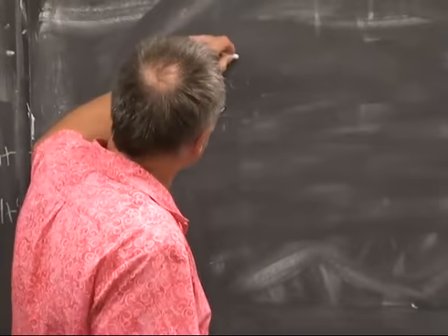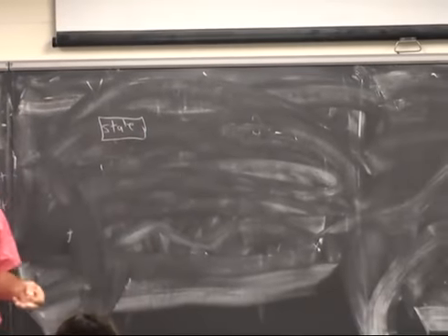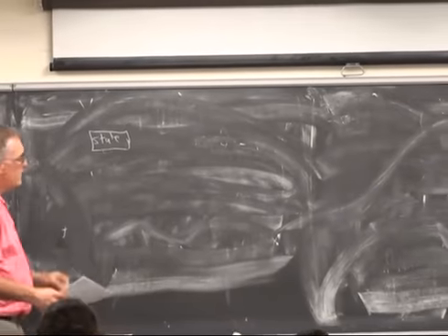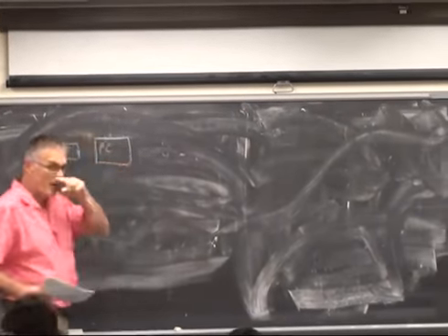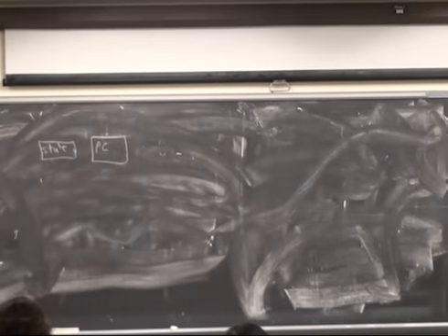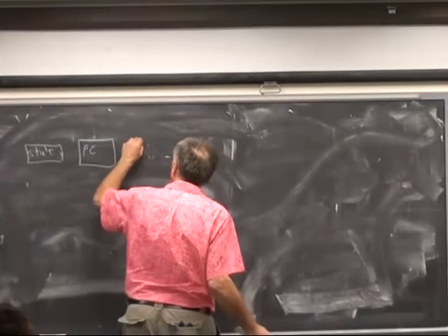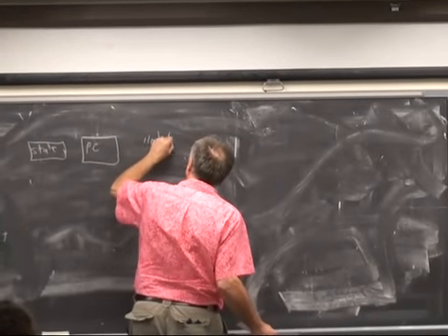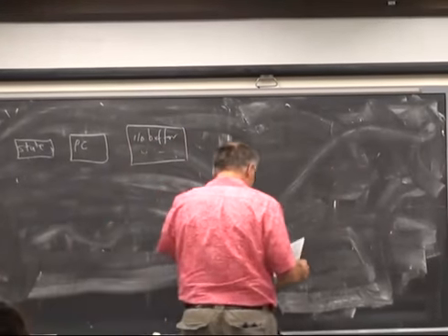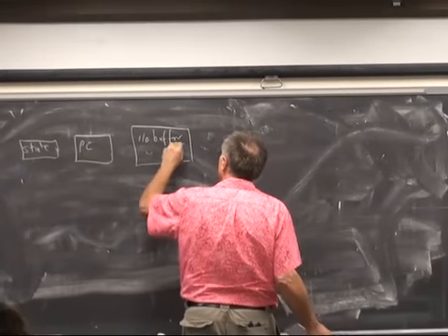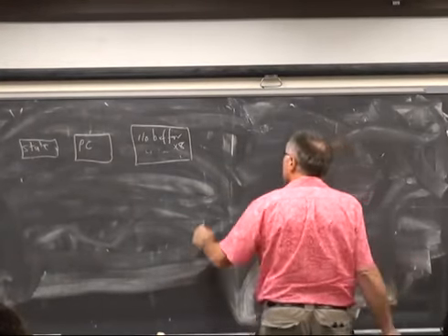So there's going to be a state register which you don't have access to. It's not part of the programmer's model. There's a program counter which you will have access to as part of the programmer's model. There's an I/O buffer, which in the implementation you're going to be using is 8-channel. And there is a stack.